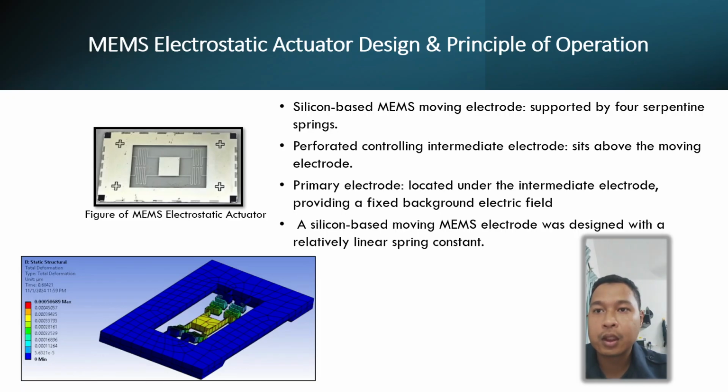This configuration allows the perforated intermediate electrode to enable similar deflection as the conventional topology, but with a lower controlling voltage. The tri-electrode topology also provides a longer displacement before snap-down occurs, larger than 1/3 of the initial gap of the conventional actuator situation. Overall, the upper part of the actuator operates based on the principle of electrostatic force modulation and background electrostatic field enhancement to achieve lower controlling voltage and extended controllable range. So we design only the upper part.